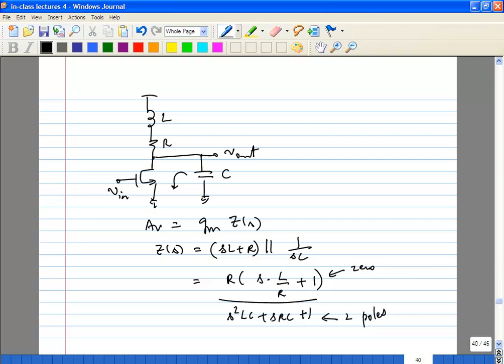You want the inductance, but you don't care about Q, because the resistance will already be probably hundreds of ohms. What you want to minimize is die area, which means you want to maximize the amount of inductance for a given area. So you will probably be using very thin lines for the inductor. Typically thinner lines will give you more inductance, and you can minimize the area.